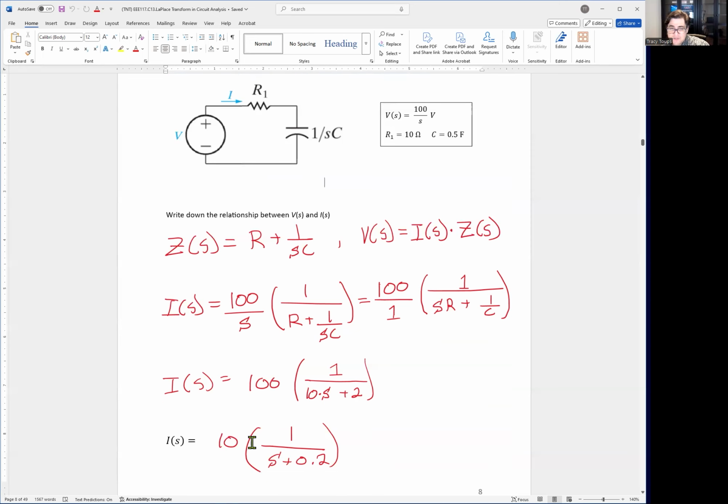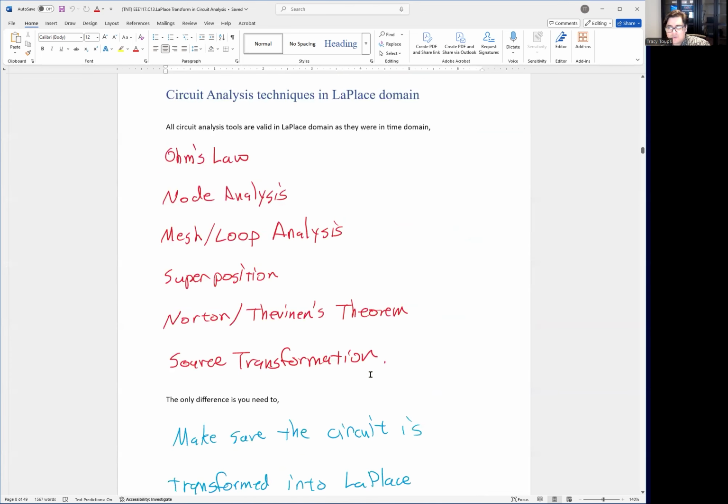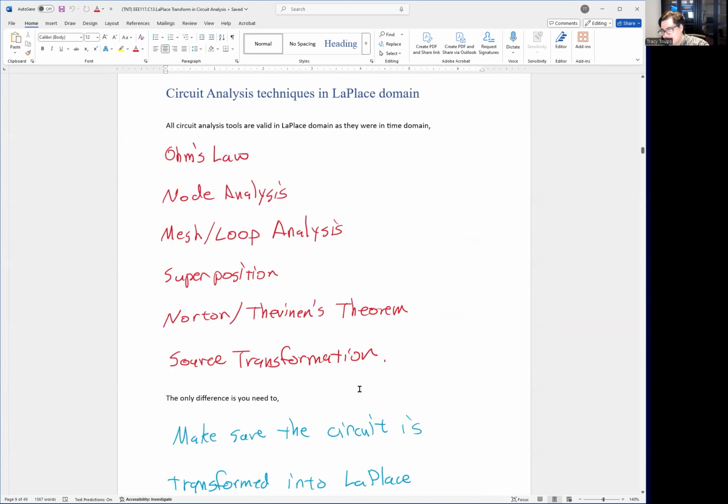And that's why you have this function. Okay, this function I is never going to change unless we rearrange the circuit parameters. So this current is locked into this circuit configuration, so you don't have to do this analysis every single time. Okay, build this into a spreadsheet and then just change the frequency in one of the cells, and you can just see the number pop up over and over again. Okay, that's the whole point of circuit analysis, right? We want to get a circuit to where we could predict what's going to happen when we use it for the next step.